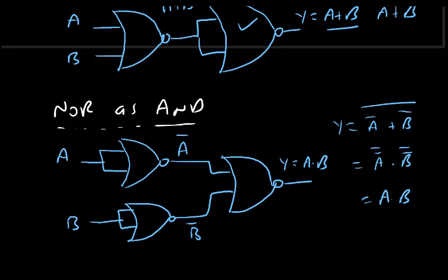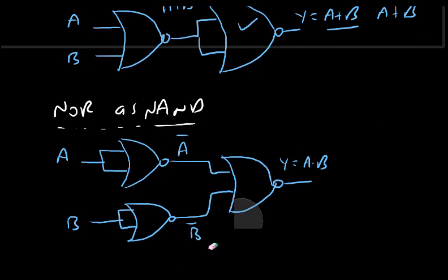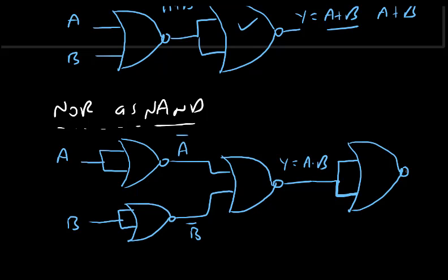Now finally, how it works as a NAND gate. So we can just make corrections here. So next is output as a NAND gate. I will just rub this one out, I don't need it. Here I draw one more NAND gate after this, which is of course shorted. So here the input is shorted, so now input is A and B and this is working as a NOT gate.